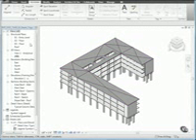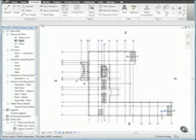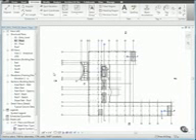Open the View 02 floor, and from the Annotate tab on the Tag panel, click Beam Annotations. In the Beam Annotations dialog, under Placement, with all beams in current plan view selected, click OK. In the Revit dialog, click Yes to turn on the structural framing tag visibility for the plan view.